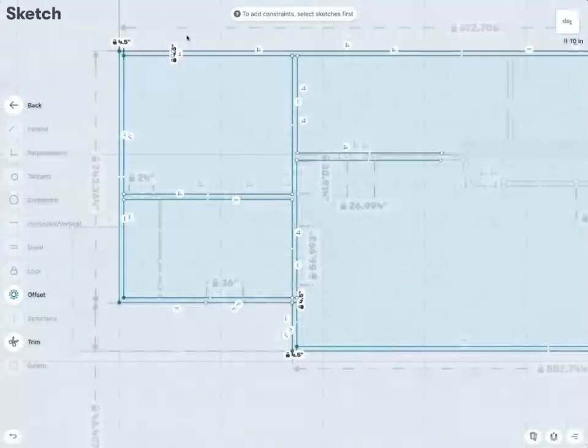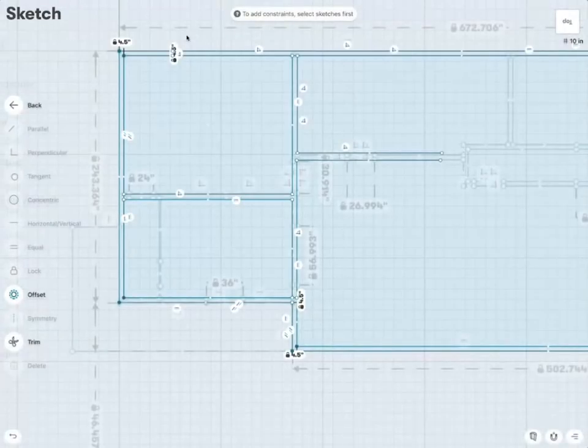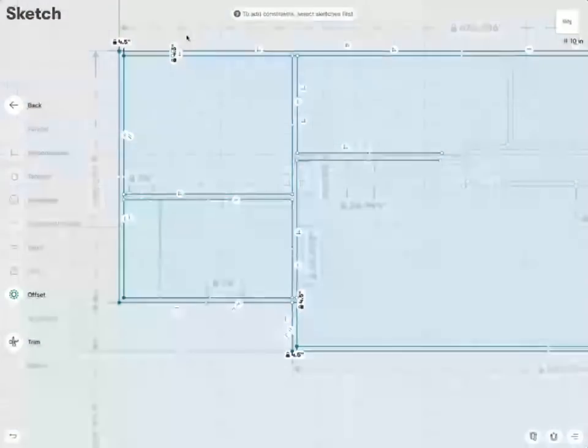So this way, via the locking of these points, you can, for example, prevent certain elements from moving once we add more constraints to them, dimension-wise or edges. Because keep in mind, with Shaper having a smart sketch solver-based engine, based on what we do, it might always deform the sketch by guessing, imagining what you want to do. And sometimes you have to help these engines a little bit by constraining the sketch more.